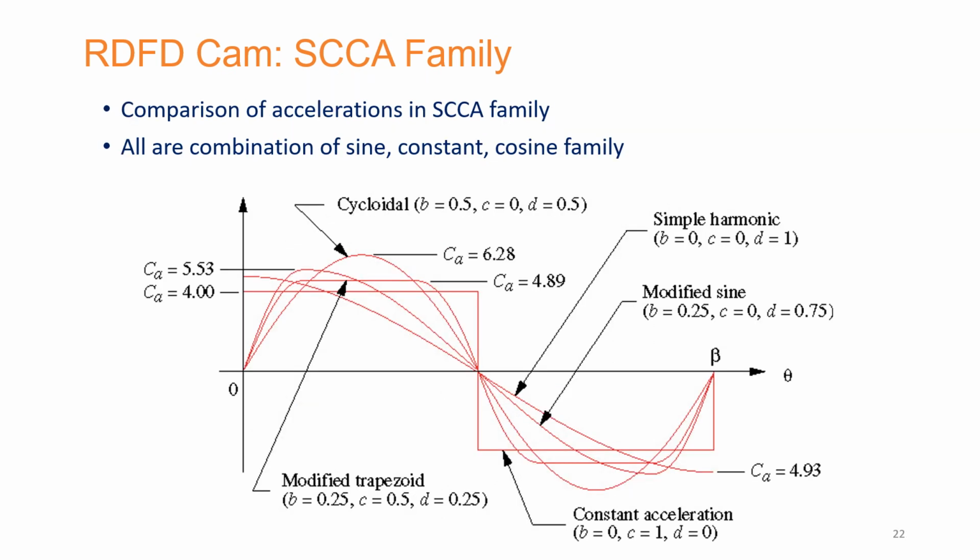And in this family, if we compare the acceleration profile, you are going to find out all the curves mapped over each other like this. Now this diagram is important because it gives you the insight, and that's exactly what engineers aim for whenever they perform certain design activity. So the very first thing that you should observe is that you have the independent axis over here, which corresponds with the theta, and you have the dependent axis over here, which corresponds with the acceleration term over here.